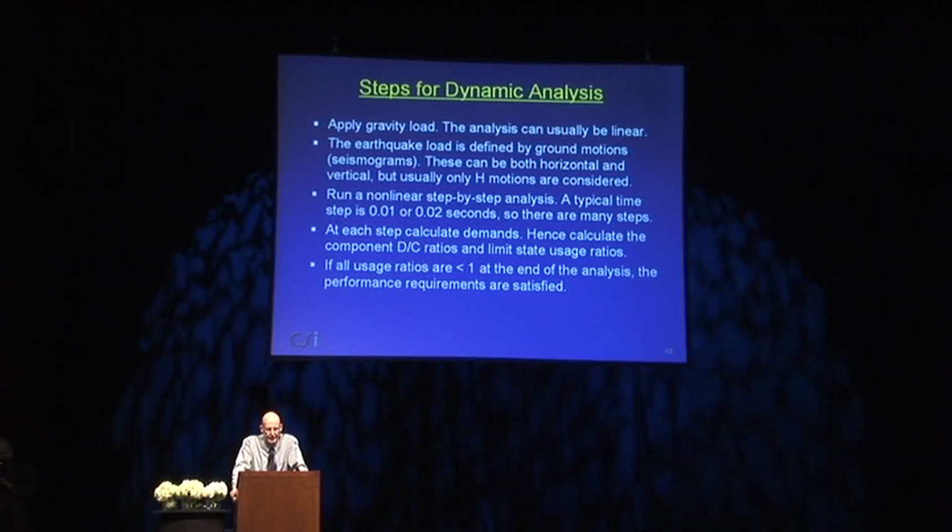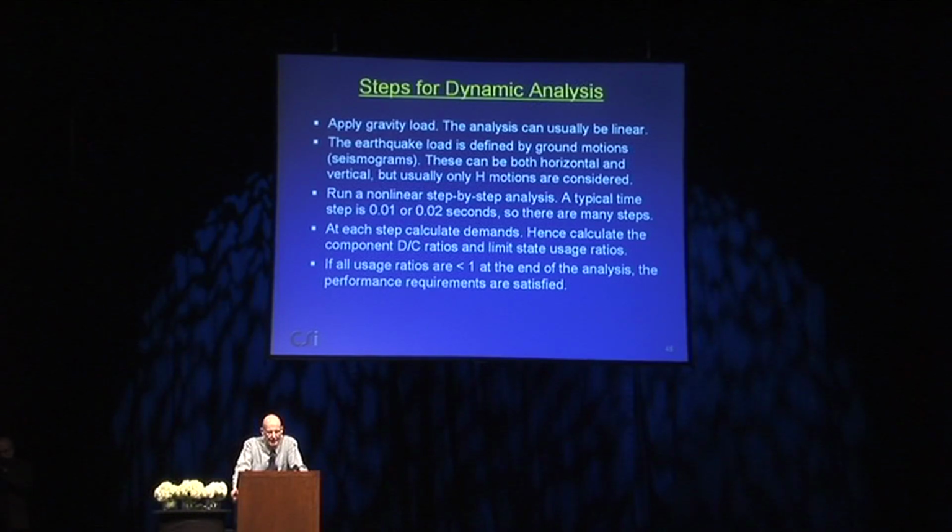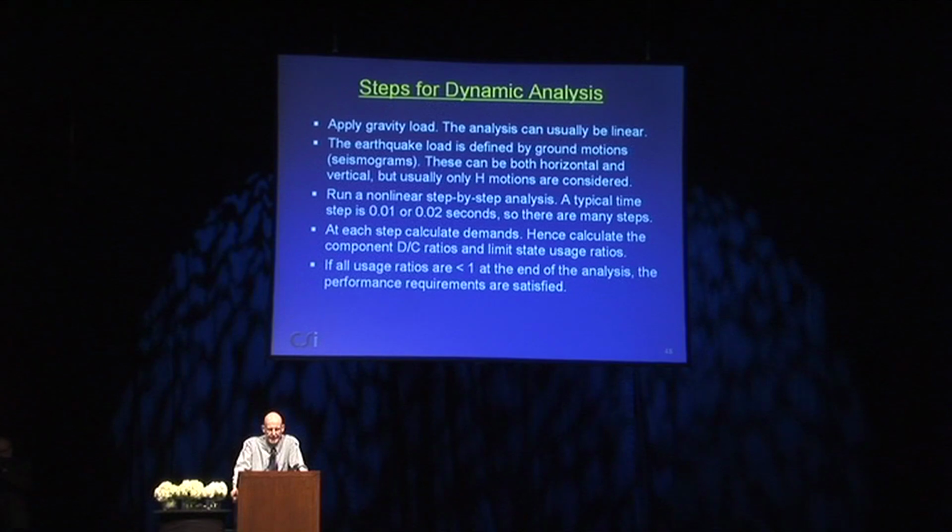So you run a nonlinear step-by-step analysis, step-by-step through time. It's a brute force approach. A typical time step might be 0.01 of a second or maybe 0.02 seconds. If you have a 20-second earthquake, it might be 2,000 or 1,000 steps. That means it's going to take roughly 1,000 times longer than a linear analysis because you're just repeating the analysis basically many times. At each step, and Perform does this calculation for you, it calculates the demands for every component. If it's 1,000 hinges, it calculates the rotation demand for every one of those 1,000 hinges.